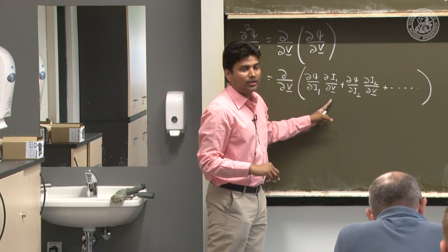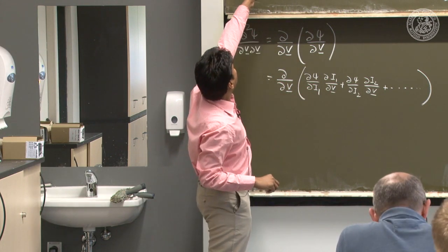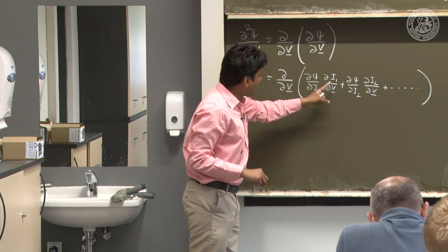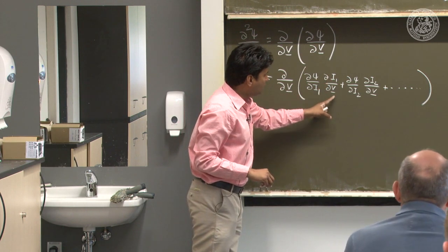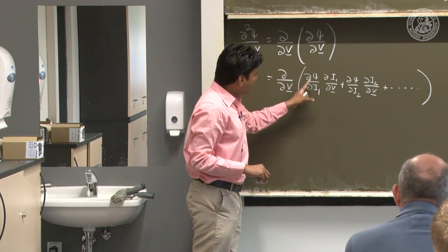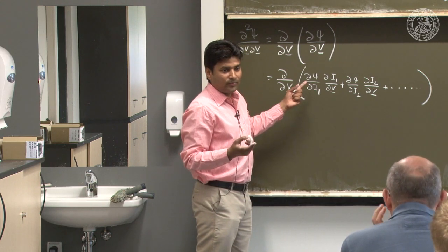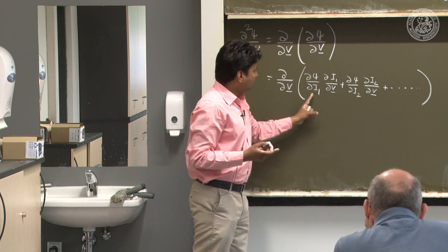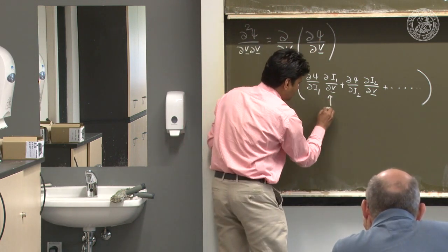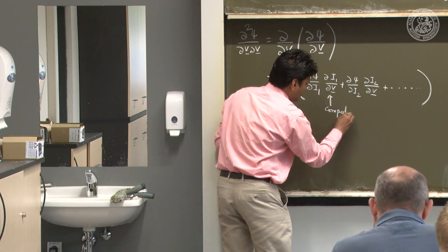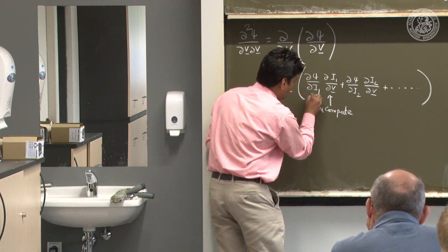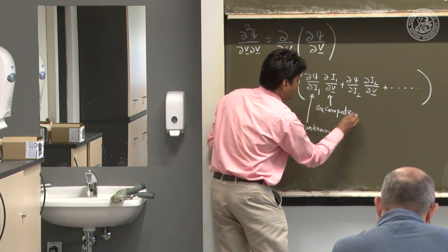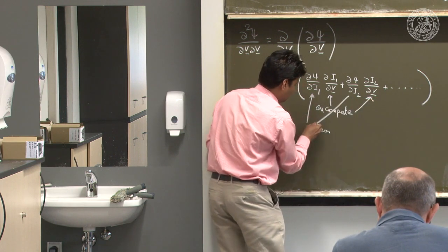And you see del I1 over del V. This is something you can obtain because I1 is V1 square plus V2 square. So you have the formula for I1 in terms of V. So del I1 over del V you can obtain. But del psi over del I1 is now an unknown, because we don't know how psi in terms of invariants looks like. So this you can compute. This is unknown. This also can compute, but this is unknown.